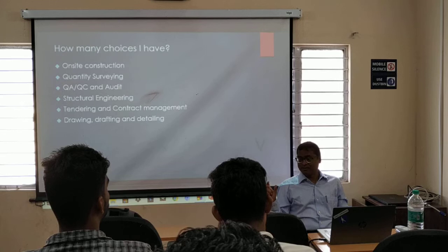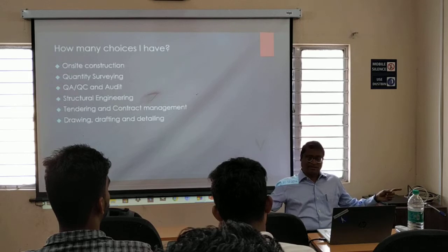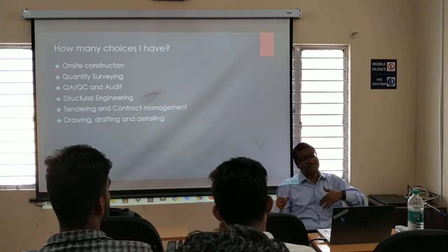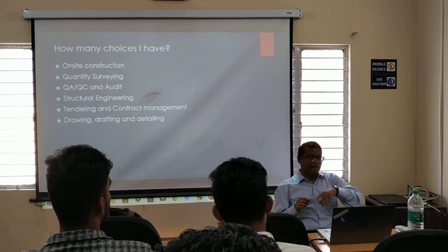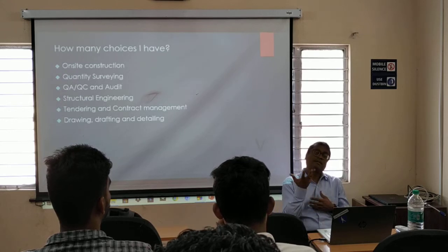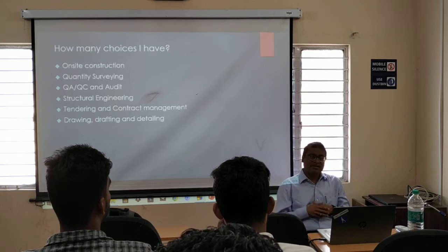Shop drawing will tell you the shopping list. What all is required for this pipeline, how many couplers are required. After 6 meters, if the shop drawing is not showing a coupler, this is not a shop drawing, it's just a copy of the GFC drawing. You should be able to procure the material from the market. The contractor should be able to procure the material from the market with the shop drawing. And the as-built drawing includes.